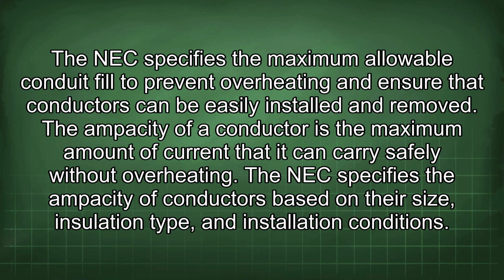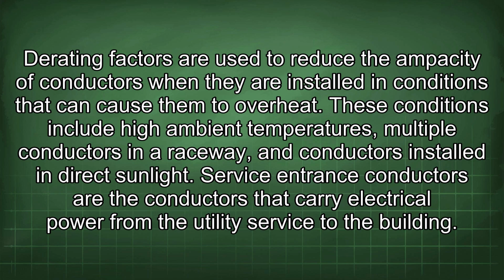The NEC specifies the ampacity of conductors based on their size, insulation type, and installation conditions. The derating factors are used to reduce the ampacity of conductors when they are installed in conditions that can cause them to overheat. These conditions include high ambient temperatures, multiple conductors in a raceway, and conductors installed in direct sunlight.